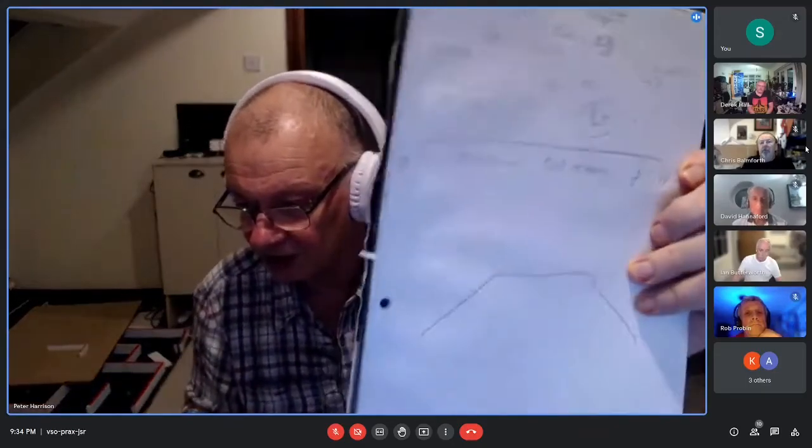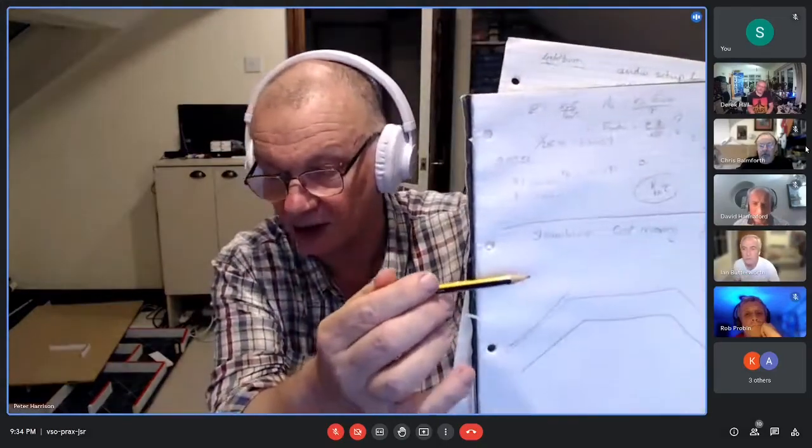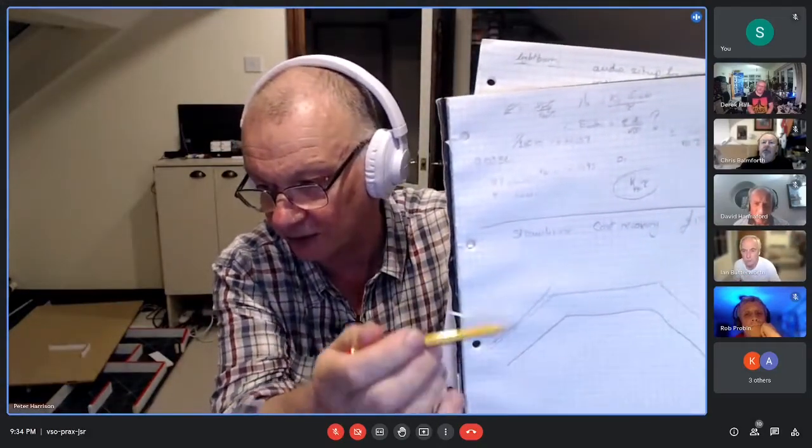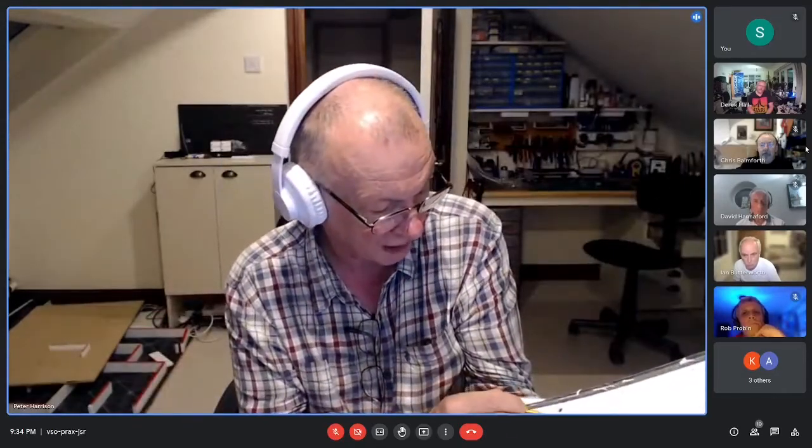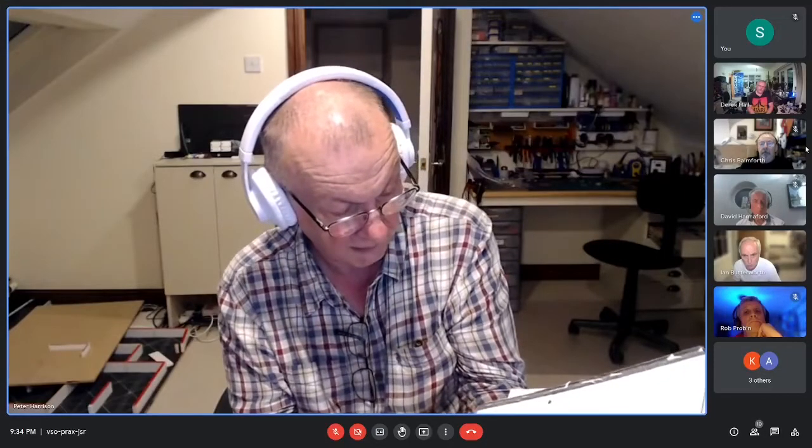So if that's the profile at the bottom, some strange angle, and remember with the feed forward, that's 0. Without acceleration, the feed forward, the top one, has no steps to it. It just starts at 0 and goes up to whatever the voltage is. And the controller previously was just wiggling along at 0. If you leave out the acceleration feed forward, the controller output will look like that.